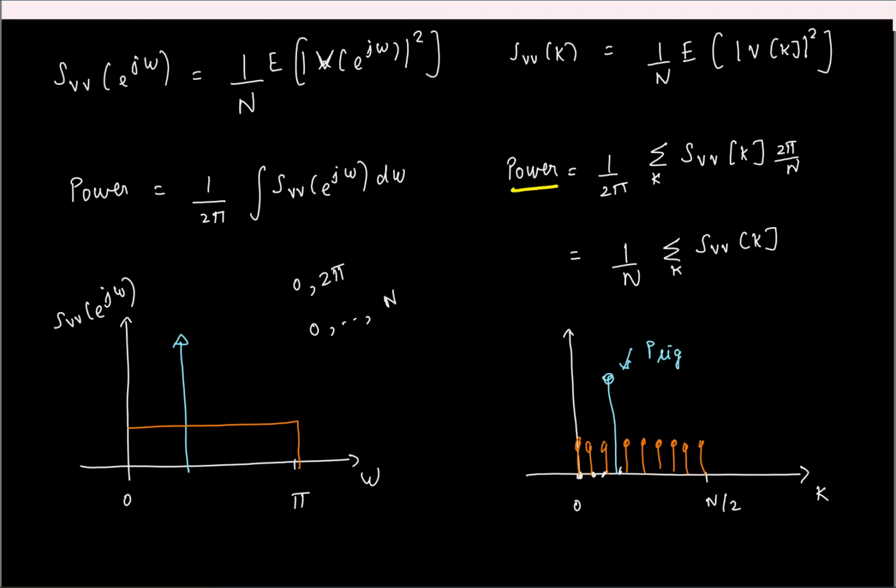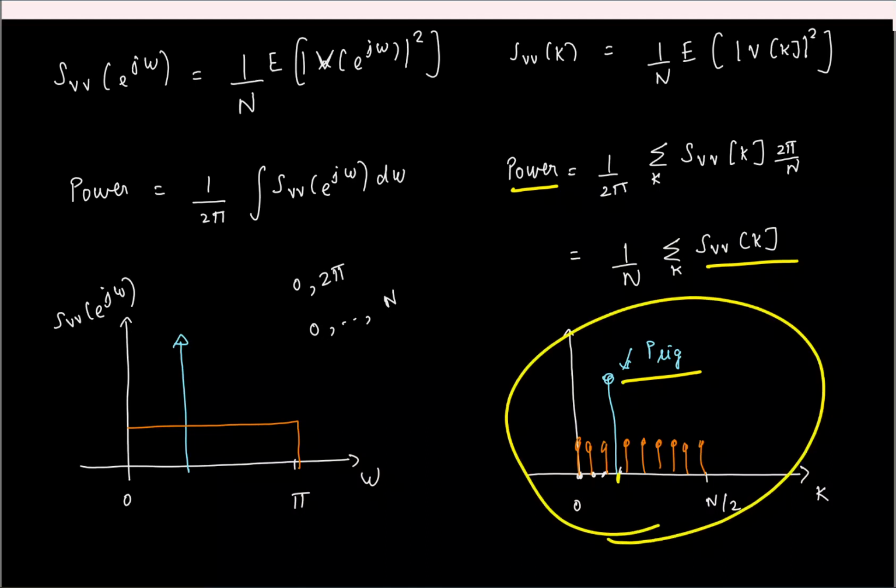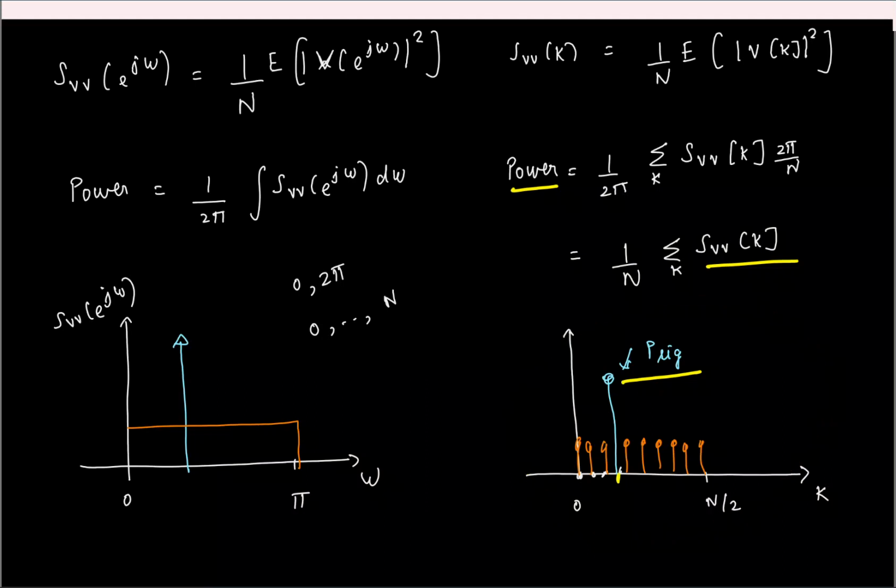No, I mean to find the power from the power spectral density, what is usually done? We have to add the power spectral density, but one bin is already occupied by signal, right? So to find only the noise power, what should be done? Yeah, you can either take the entire power by summing up everything and subtract the signal, or, that's equivalent to saying that I'll sum up only these bins, right? If I take the sum of the entire PSD, I get the total signal and noise power. I'll have to subtract the signal power, which is basically this alone. So instead I'll sum up the content of all the bins except the bin on which the signal is lying, and that gives the noise power. So then you take the ratio, you get the signal to noise ratio.